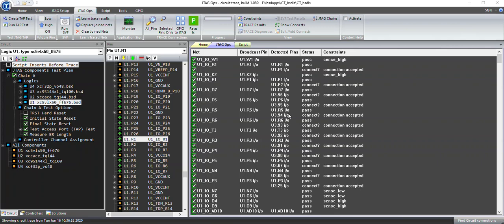However, of course, the thing to be aware of is that we're transmitting signals throughout this board without regard to what constraint should be applied. We might be trying to transmit from a pin that controls power, or that might cause contention, that enables memory devices, or that affects bidirectional controls, the direction control on such devices, buffers, transceivers, any number of things in the circuit.